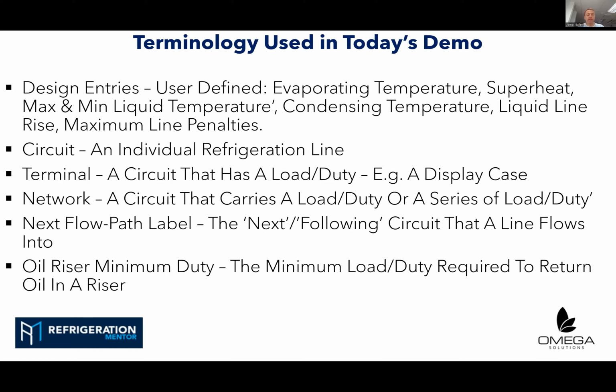But the upside, and it's a big upside, is we can save energy, we can save consumption, because that rack is going to operate more efficiently, at a slightly higher saturation temperature. Every one degree Celsius that we save is 3 to 4% energy.